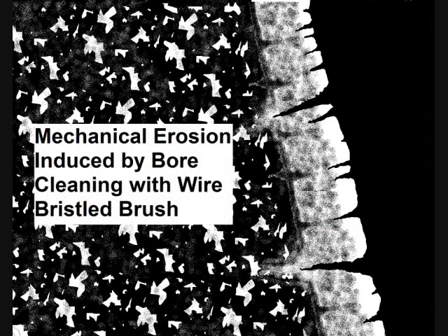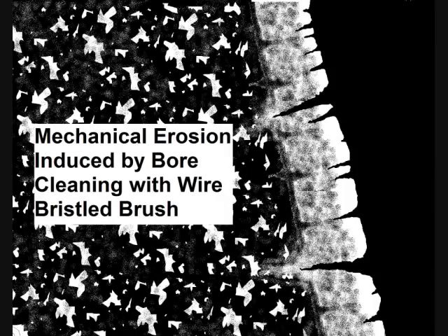If you introduce a wire brush to your bore with solvents in there, you're going to remove a lot more material than just the copper and the propellant residue. There's going to be that, like we talked about, chemically and thermally affected zone. So you are going to remove steel from your barrel when you're cleaning as well. You're not going to see it because it's on the microscopic level, but it's going to actually remove more in most cases than your normal coppering issues would have. So basically, just normal coppering is going to remove less material from your bore and alter your bore less than trying to clean the copper out of it would have.